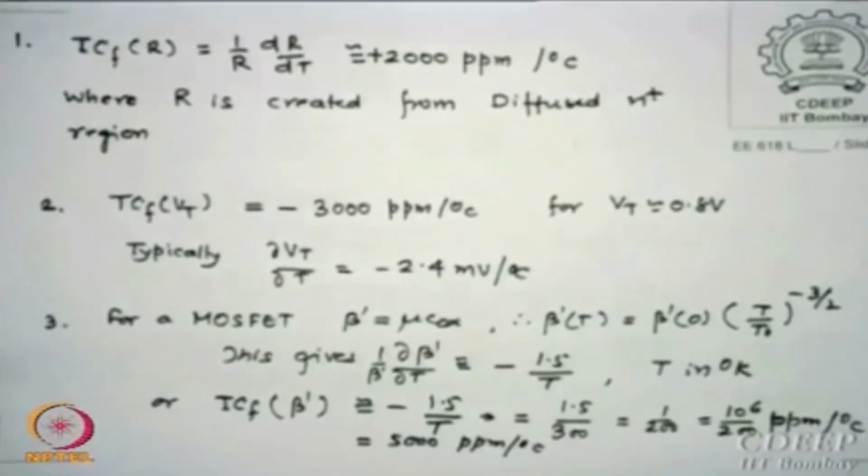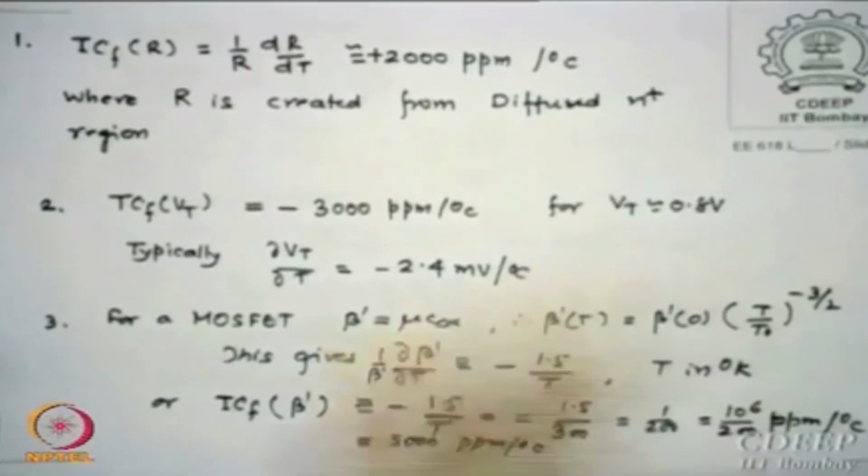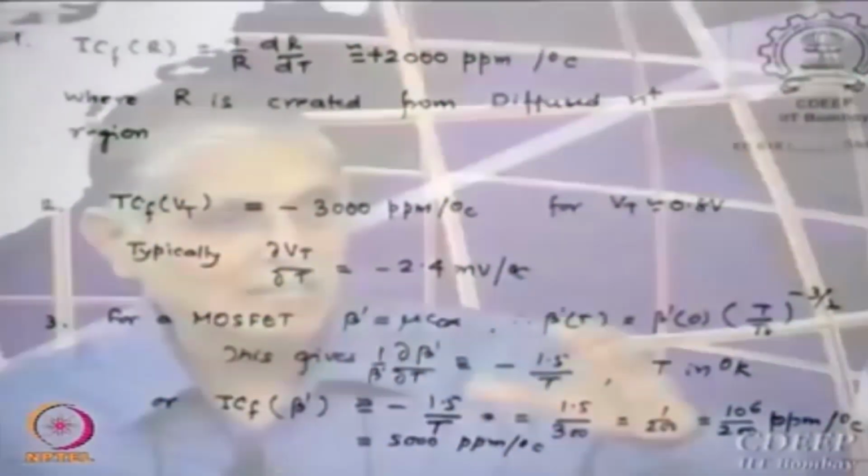Okay, now we have seen sensitivity due to power supply and sensitivity due to temperature. So now when I am designing a current source, all these areas are in my mind. How much current I want, how minimum voltage I want, how much RO I want, and how much is the sensitivity for both VDD and temperature I have. Based on that only my design will be a good current source, is that clear?